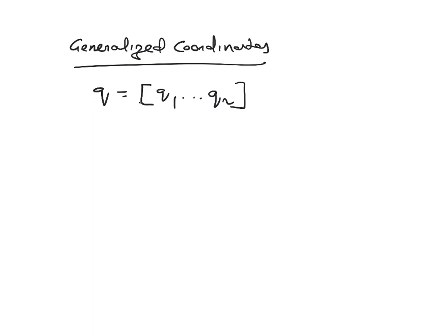So remember these are R, and that's the first step, the most important step. You figure out what are the generalized coordinates of the particular system that you are trying to model, right? The next step is to get the total kinetic energy in the system, okay? There may be different moving parts in the system, so you basically sum up the total kinetic energy.